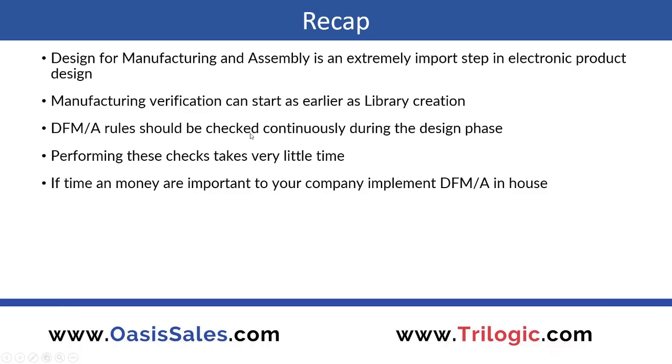So DFMA rules can be checked continuously during the design phase. I showed that in the flow chart: don't wait till the end to get these types of DRCs and violations found and captured, because then you have to go back and spend a tremendous amount of time fixing them. Performing the various checks takes very little time, as I showed using Expedition or using the Valor tool itself.